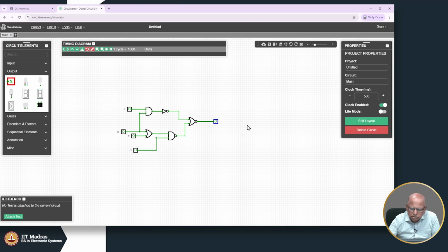So this is what a good circuit is doing. Okay. When I apply 0, 0, 0, 0, the good circuit simulation shows that it produces a 0. Okay. Now I want to inject a fault, let us say a stuck at 1 fault here. Okay. So we will see whether that stuck at 1 fault can be sort of caught by this guy.